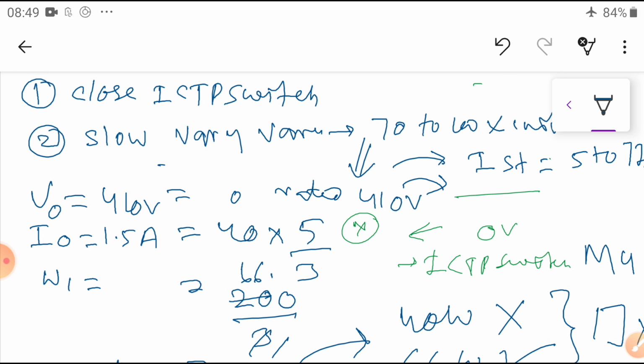For example 40 watts, and W2 maybe 20 watts. These are the readings. Based on the power factor, one of the wattmeters may show a reverse direction. At that condition, you have to change the CC coil or PC coil terminals, then take the reverse of that value. That is the procedure you already know.